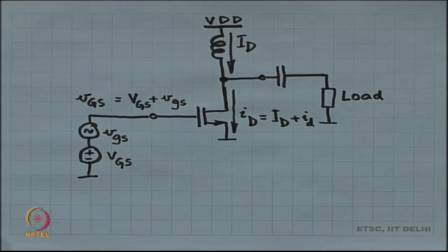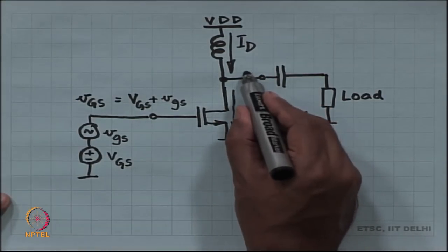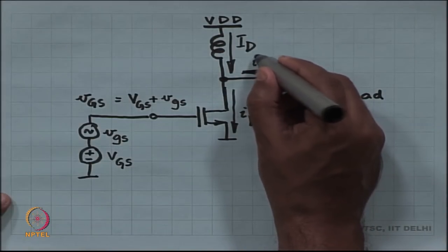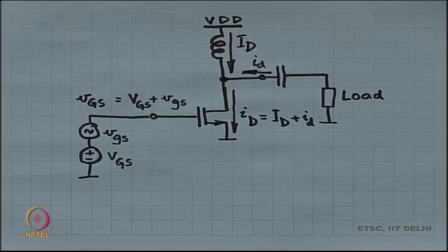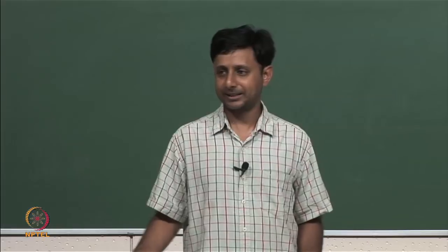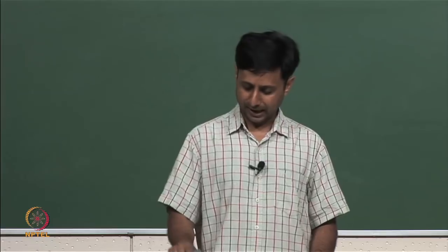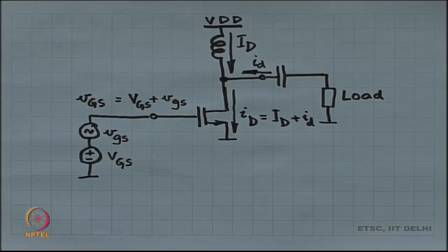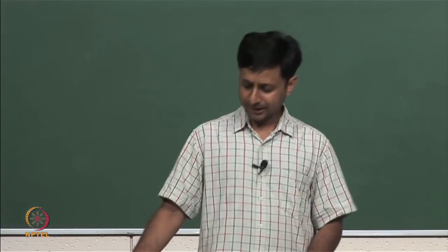And naturally what is going to happen is that the incremental current is going to come solely through the capacitor, small i subscript small d. And remember, the capacitor is a short circuit for incremental signals. So, the incremental current will happily come through it, but it is an open circuit for DC, which means that capital ID, no portion of capital ID can come through the capacitor. Okay. So, we have cleanly separated the signal from the DC operating point over here. It is very clean. All right.